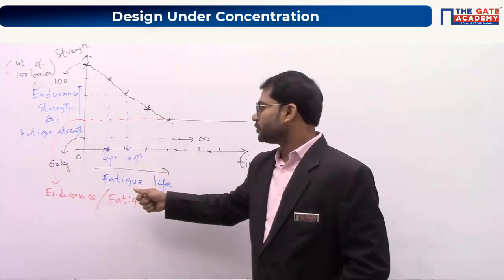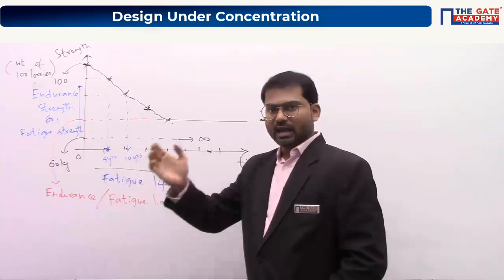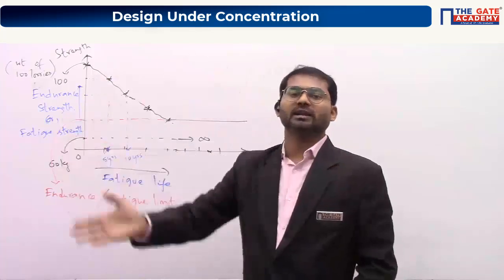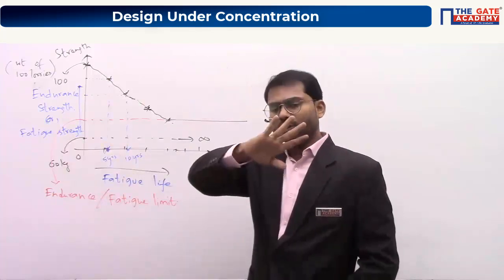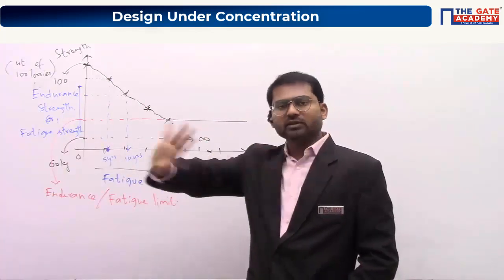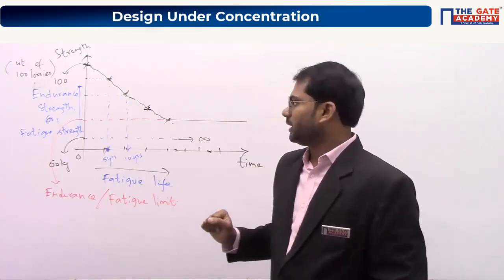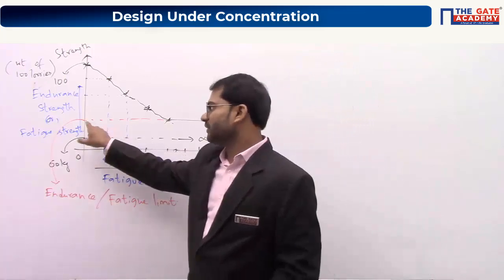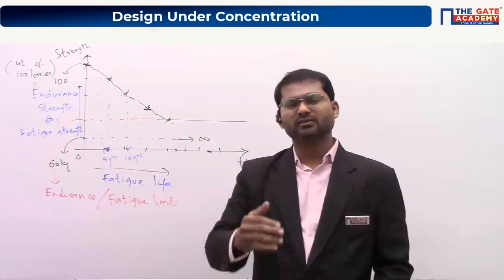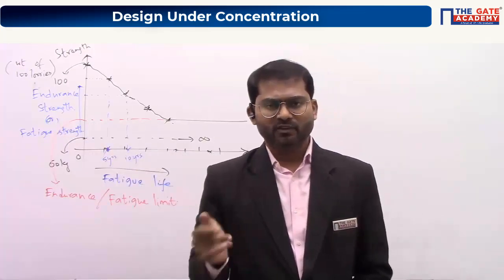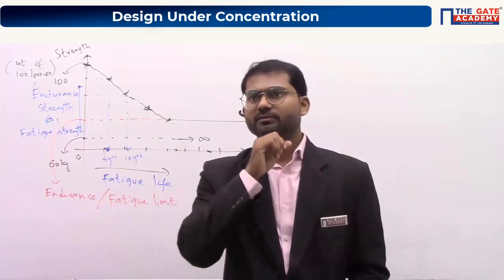So endurance limit is nothing but endurance strength corresponding to infinite life. So below that value, you will have infinite life. The component will never ever fail at all. Okay, but unfortunately, the endurance limit for any material for any loading condition will be very, very less. For example, I'll put it this way here.